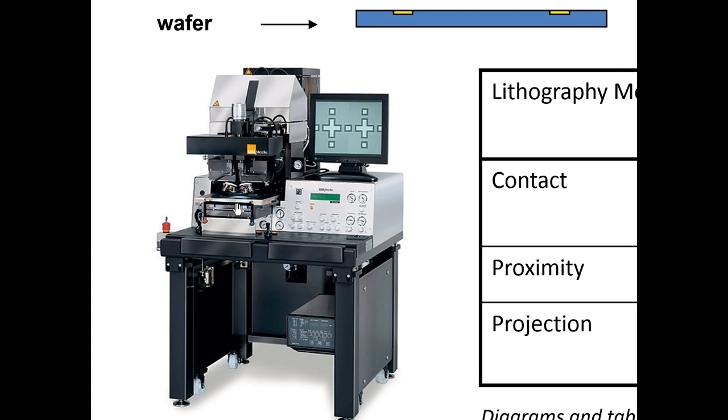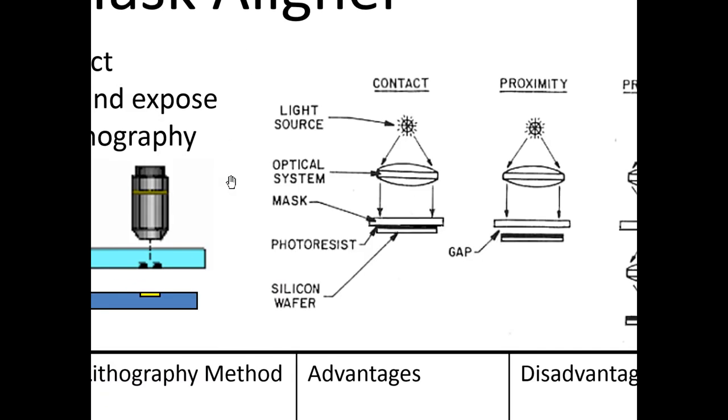This portion here is controlling the exposure. So if you look on top here, this is an ultraviolet light source. That's what those warning signs are. There's an ultraviolet light source here in the back. There's optics up here to make sure that the light is collimated. So what you have coming down here is collimated ultraviolet light. Okay, and according to this diagram here, this is a contact mode lithography system.